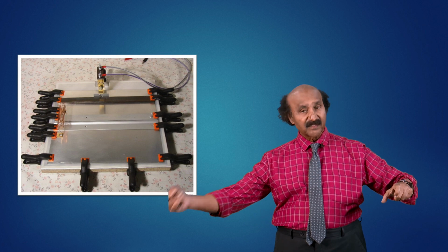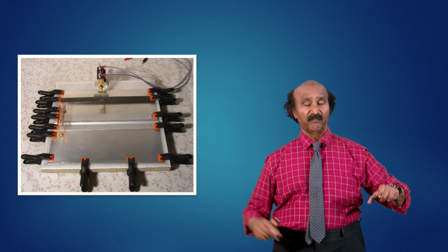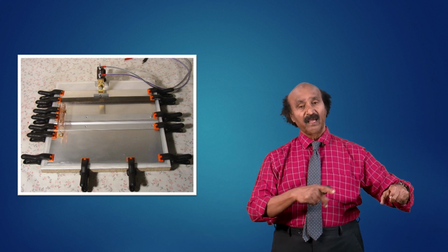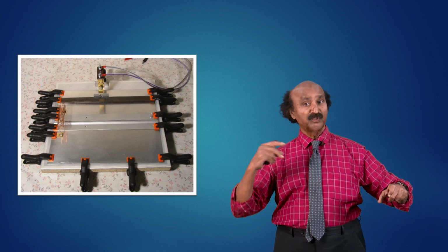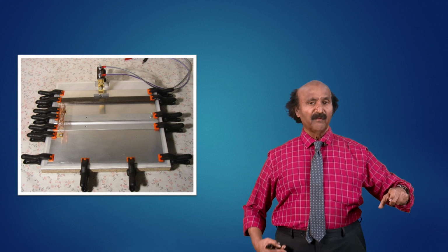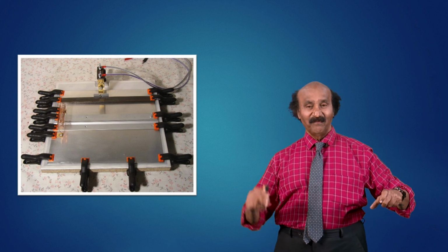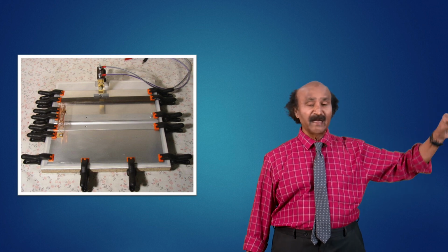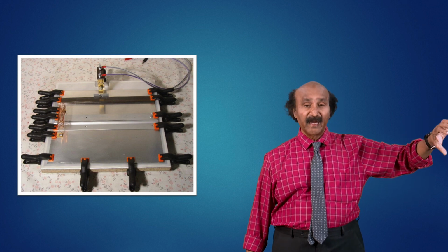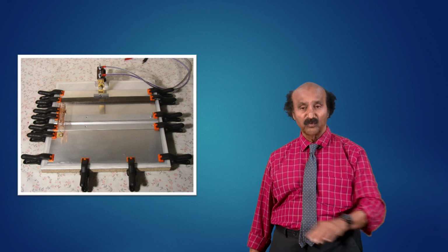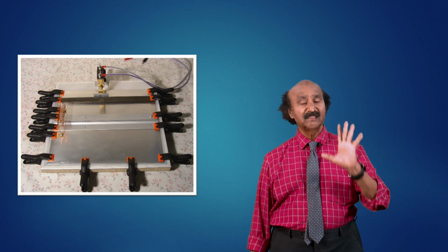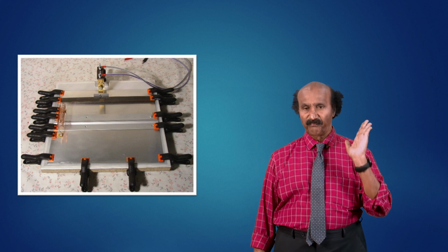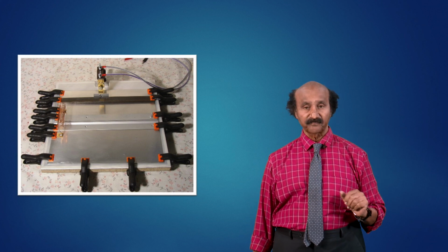Then on the other side you have a vacuum pump. If you use the vacuum pump, it will remove all or most of the air. We do not have to remove it completely; we remove most of the air and then keep allowing the nitrogen gas in. Then nitrogen gas will be flowing through. The pressure inside can be about 1 or 2 torr, that is all. We need that kind of pressure, that is all.